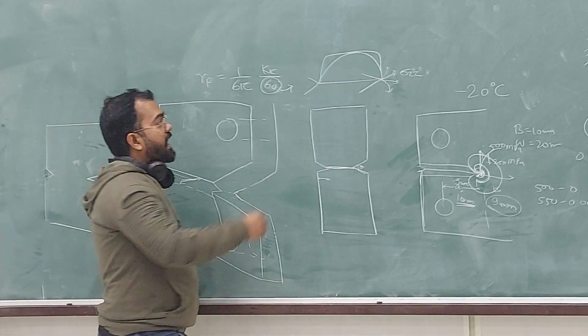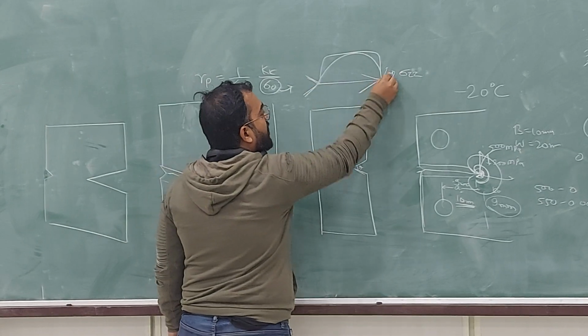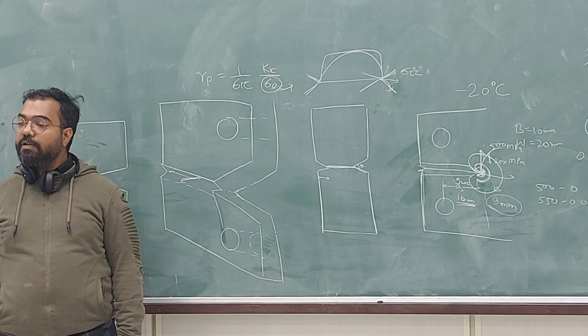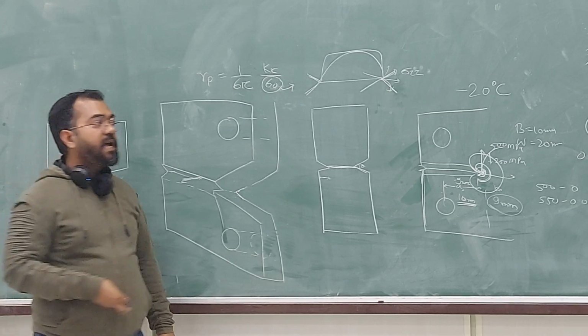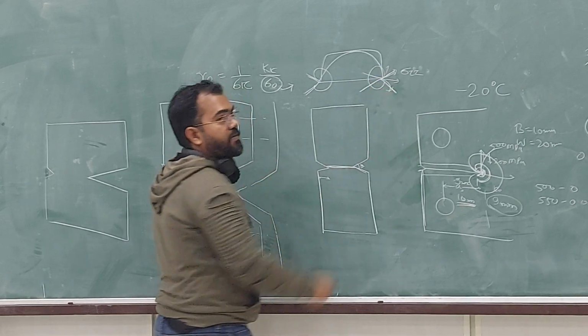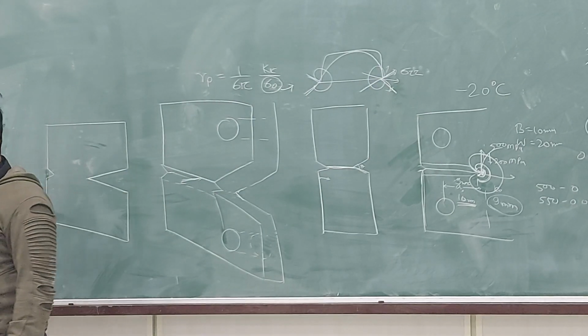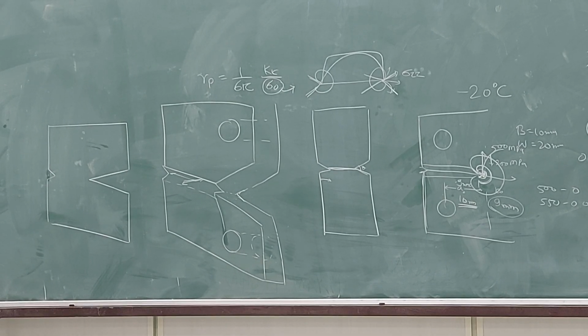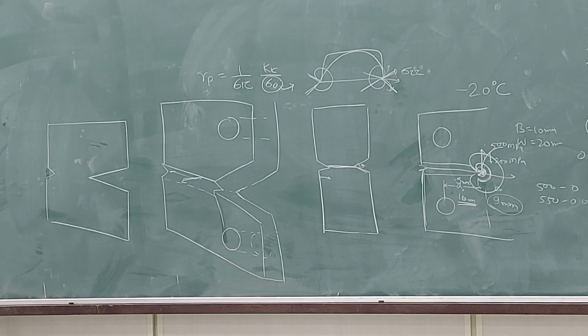Okay? And creating a notch is also creating a crack. By creating notches on the surfaces, I am increasing the stress here, because there will be a plastic zone here also. There will be a stress asymptotic behavior if I create a notch on the sides. So I am elevating stress by creating these side grooves.